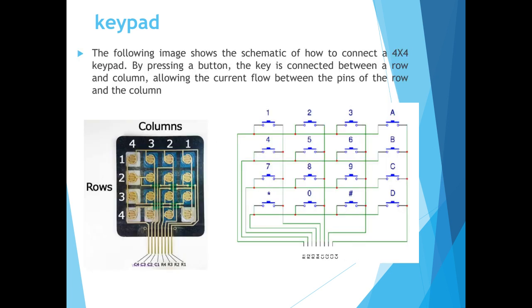Am I clear? Then we can understand why we are using a keypad instead of ordinary keys, because it gives an opportunity to use fewer pins for interfacing the same number of keys with the microcontroller.